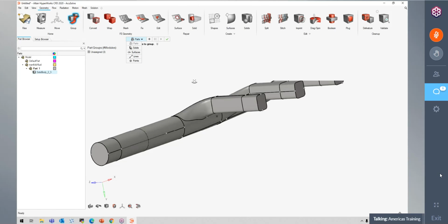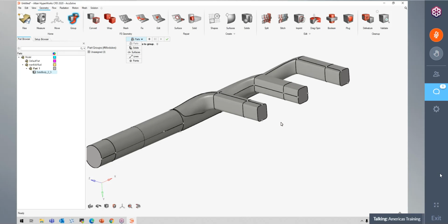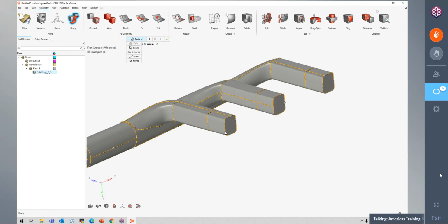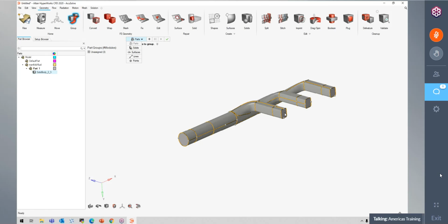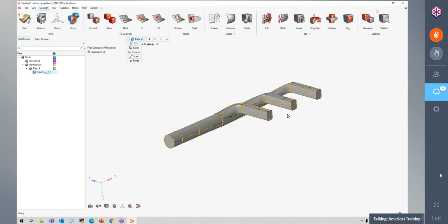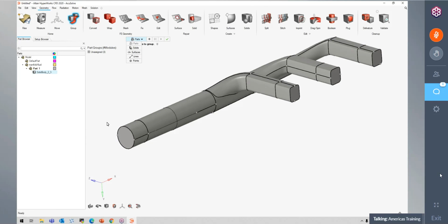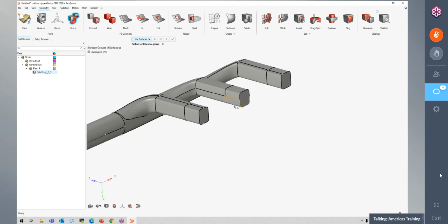In this case, for example, let's say I know that I'm going to set the same inlet velocity for these three pipes right here. Let's say those three are going to have the same boundary condition, whether it's an inlet velocity or whether they're all outlets. I think in this case, the inlet is on this larger side on the left here. So this is where that inlet would be, and the outlet would be these three points right here.